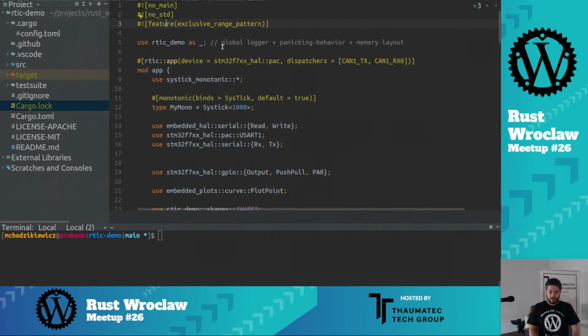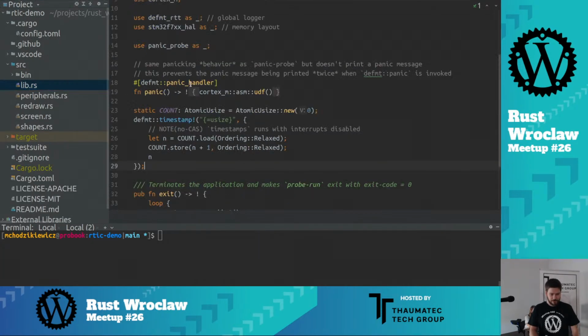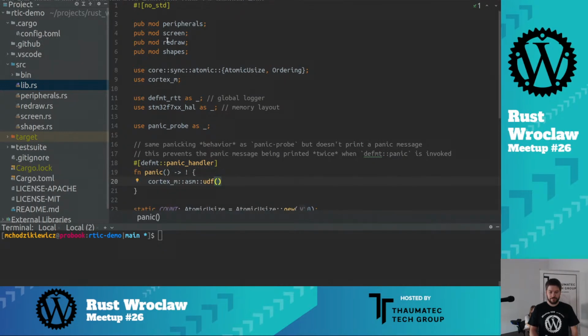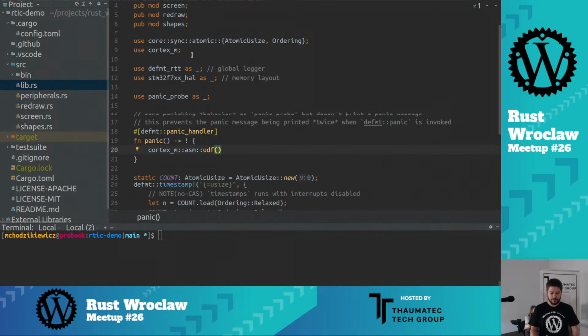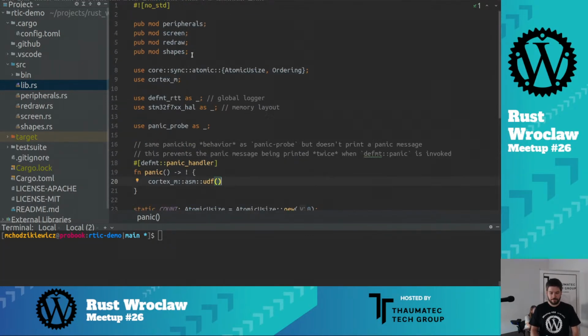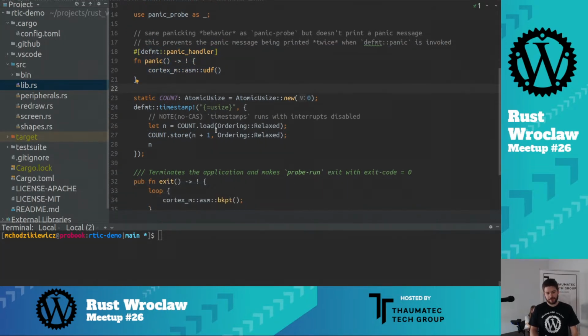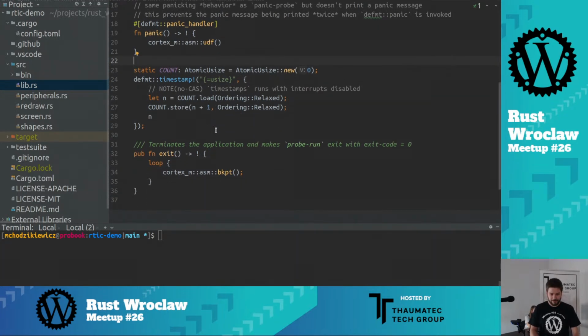We use, okay, an import from another file, and this file provides some things that are necessary to make this defmt deferred formatting work. That gives some dependencies to RTIC. For example, it also gives you the panic handler that is compatible with deferred formatting. So even panicking can be deferred, even though it might not be that big of a deal.